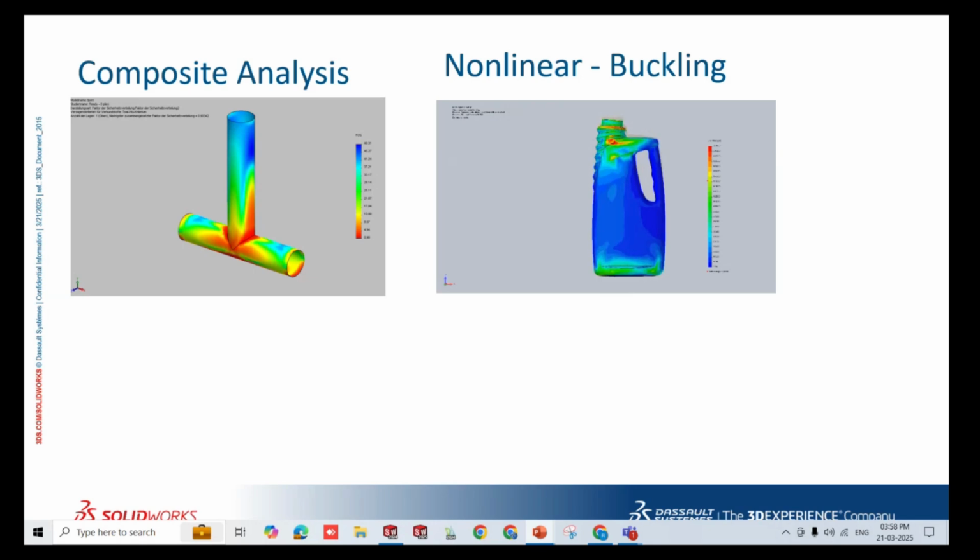First we need to understand that linear buckling does not say how the distribution of loads looks, what the actual displacements and stresses are. To know that, and to get a more accurate picture of the behavior, you need to go to nonlinear buckling analysis.